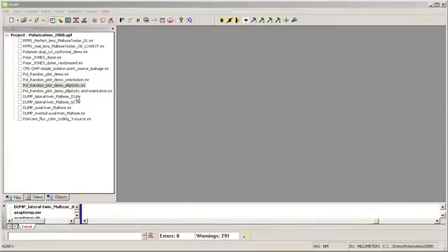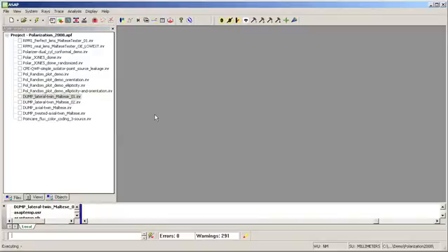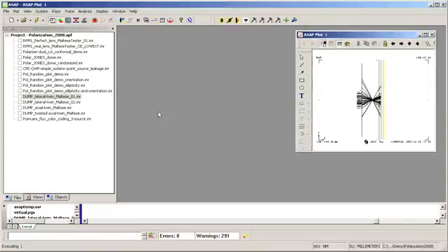So now let's take a look at another new source feature. We now have the ability to dump a source file, including polarization information, and reload that source. In this case, I'm going to make twin sources by tracing a single source, capturing that using the dump command with polarization, and then load that polarization field back in twice with slight offset between them to see what twin sources with a lateral offset would do.